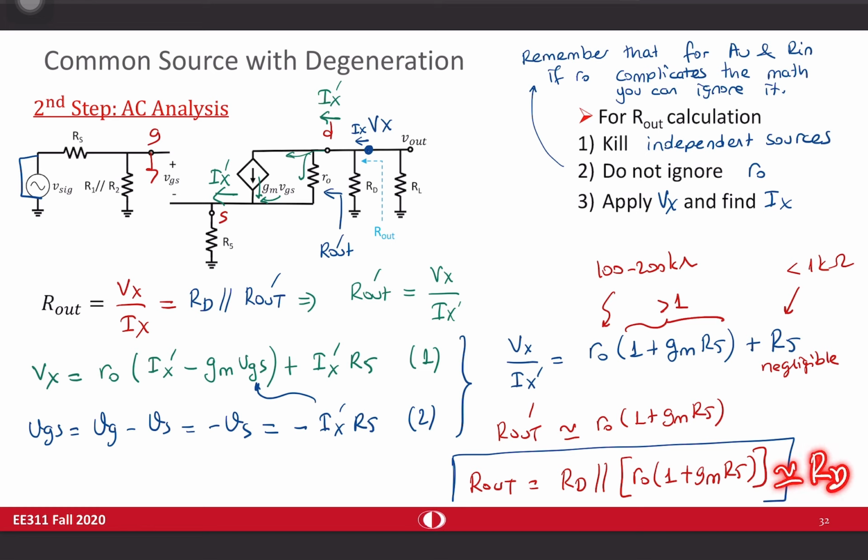If you want to set the output resistance of a common source or common source with degeneration amplifier, basically you would choose RD accordingly. But this RD value affects the gain, of course, so you have to compromise. For large gain, you can use large resistance or large output resistance. You can use large RD value, but this may threaten the operation point of your transistor, or this may result in some biasing problems. While designing, you have to optimize it accordingly.